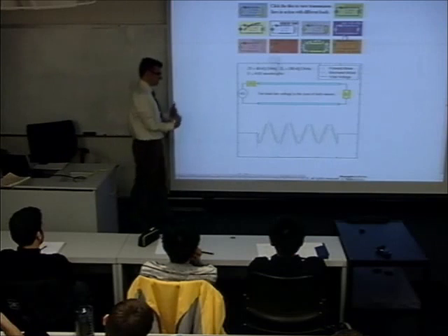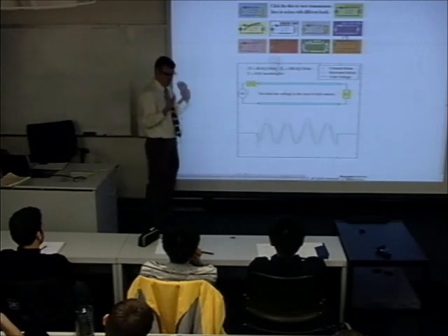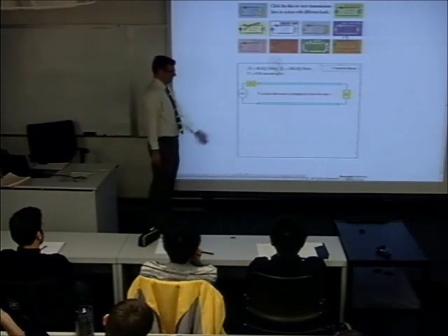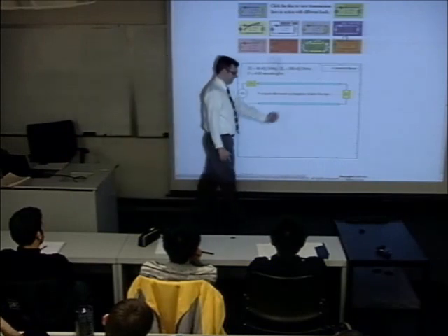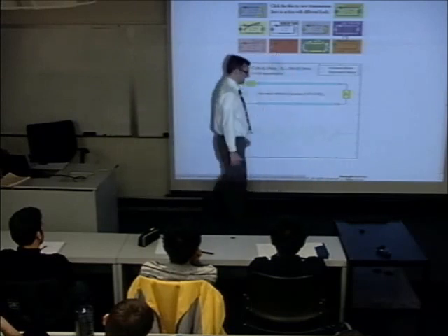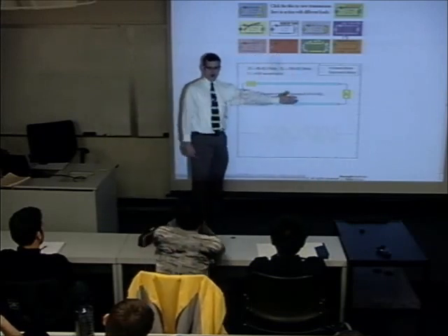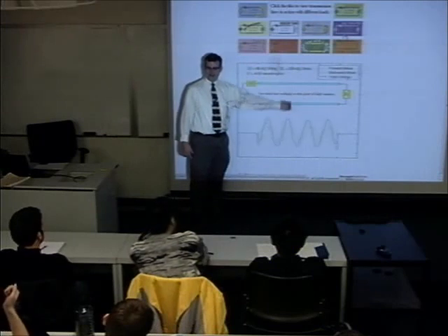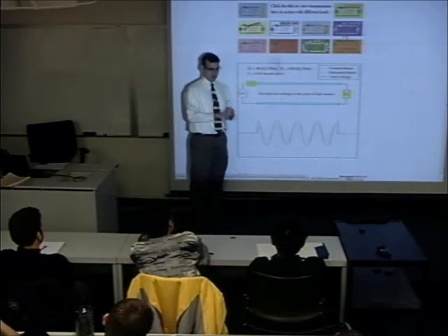It's almost always good to try to minimize VSWR because it represents reflected power. If you've got an amplifier here and an antenna over here on the load side, you want your power to all go to the antenna and radiate out. If you've got a significant amount reflected back, that means a couple of bad things. First of all, you're wasting power, obviously.